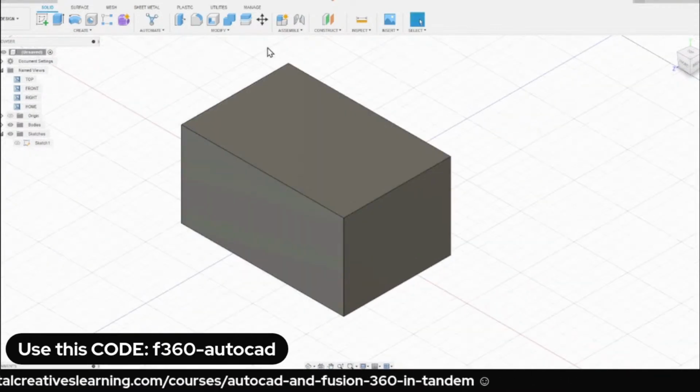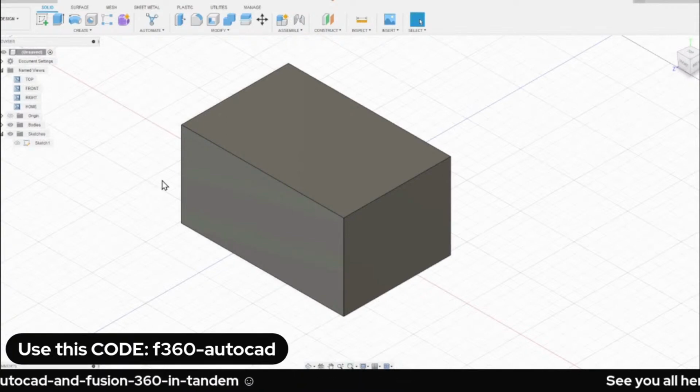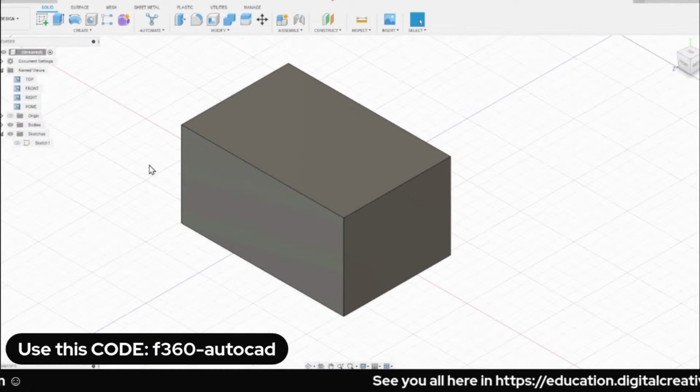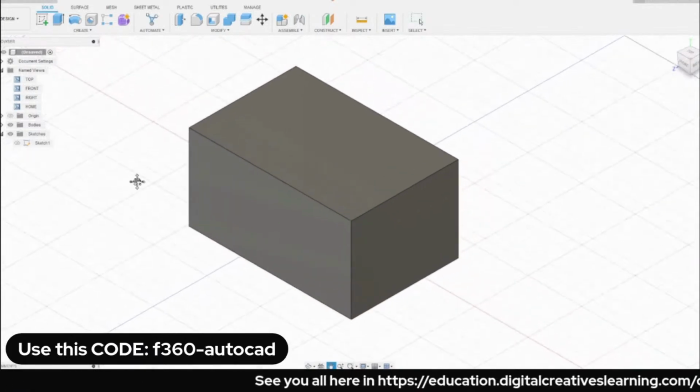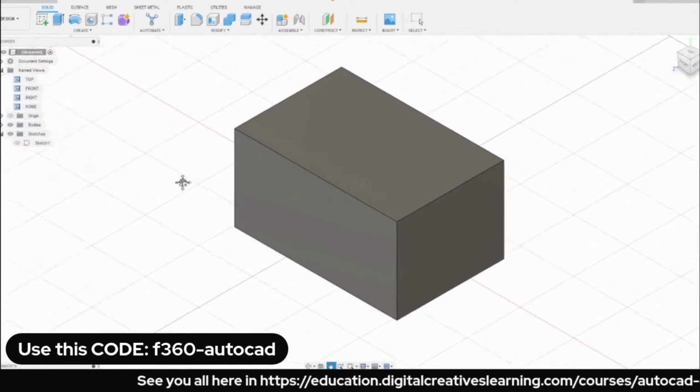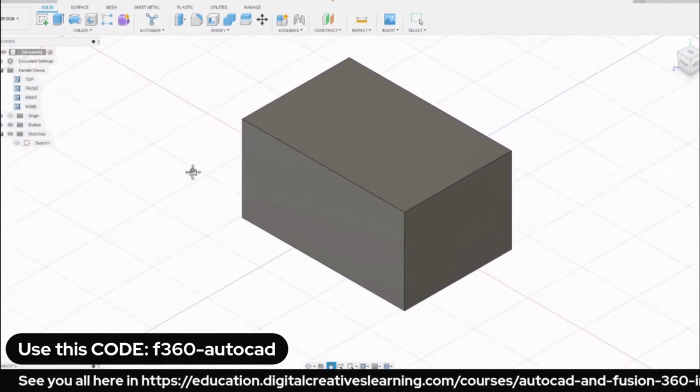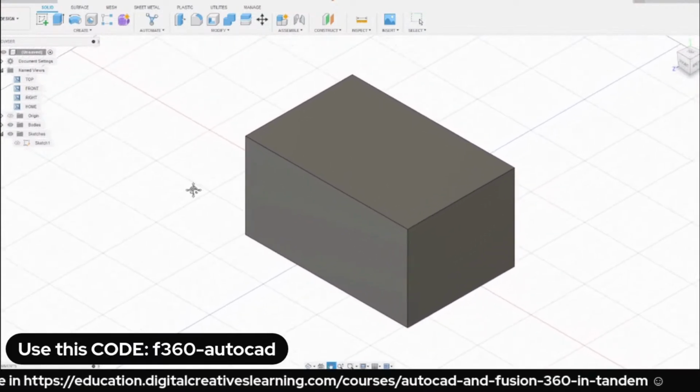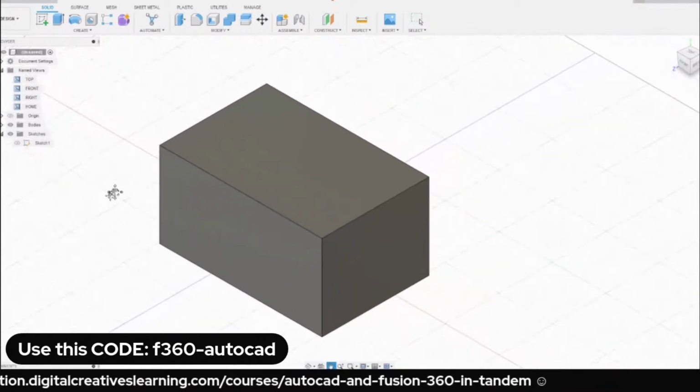So the controls in Fusion 360, of course, is same with AutoCAD. So if I hold my mouse wheel, I'm currently pressing it down. So similar to AutoCAD, I'm doing a pan. So notice the change of my cursor. I'm now panning.